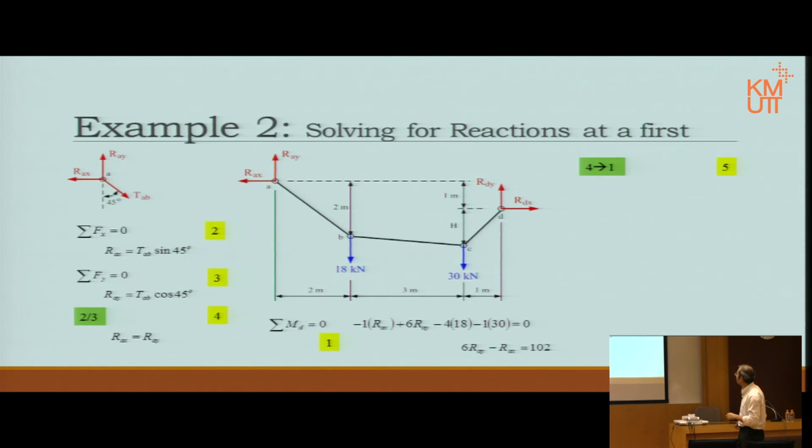If I substitute equation 4 into equation 1, then I get the value of RAY. Once I have the value of RAY, then I can have the value of RAX. Now, before we move on, as I mentioned before, when we take components in the x direction, the same number tends to pop up. We're going to prove it in the next lecture, not this lecture. However, notice that in this problem, last time it was 17, right? This time in this example, the number 20.4 will keep popping up when we do sigma, the component of the force in the x direction, horizontal line.